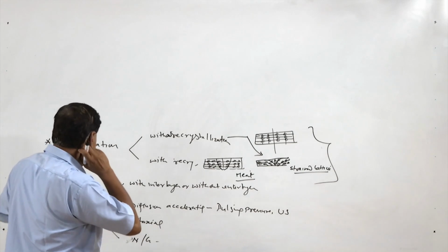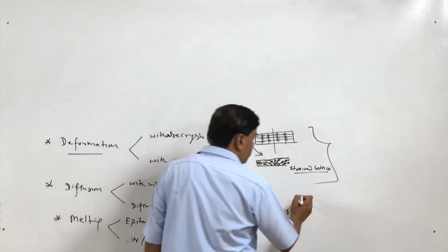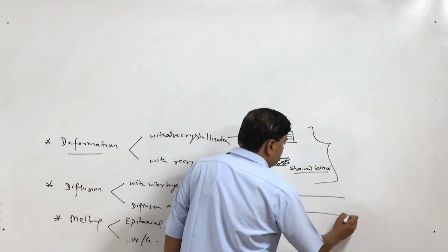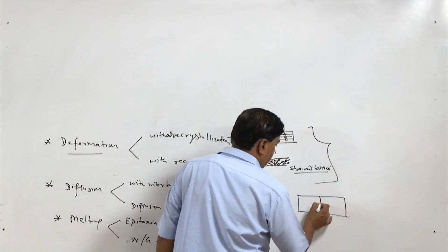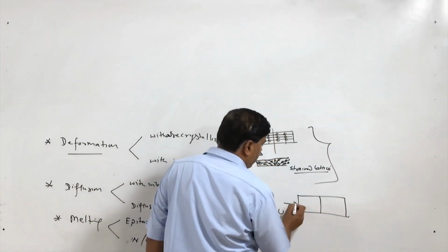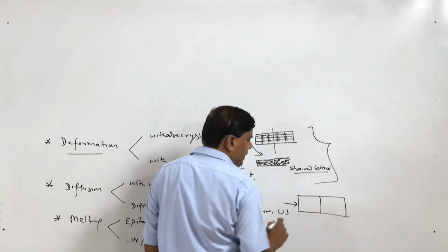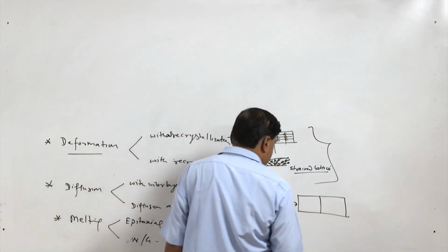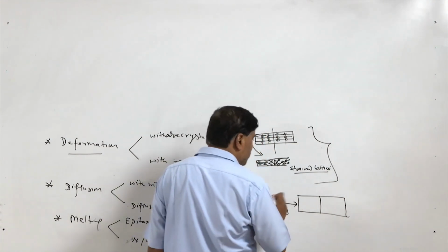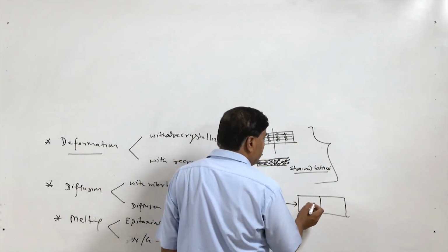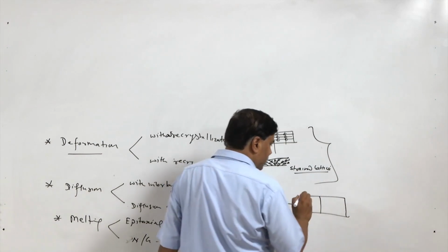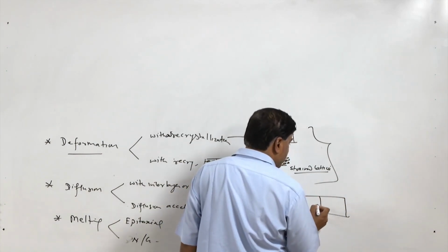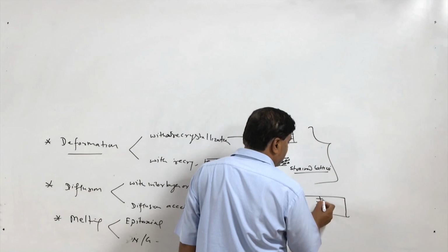In case of the diffusion, the components to be joined, in very clean polished condition, are brought together and kept under pressure, usually in vacuum, though it may also be in an active or inert environment. When there is direct metallic intimacy, due to the concentration gradient of the elements across the interface, the diffusion starts across the interface.